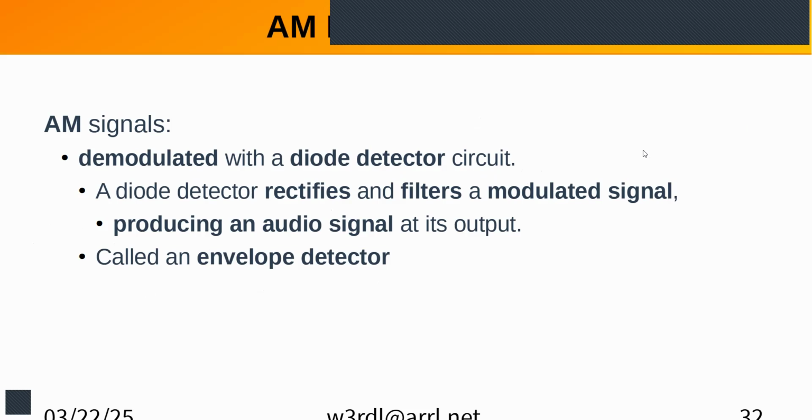Okay. So if I got an AM signal, I can demodulate it with a simple diode detector. Just a diode and a filter for filtering the high frequency out. And I'm recovering the envelope of that modulated waveform. I'm throwing away the carrier. One side of that envelope, yes.